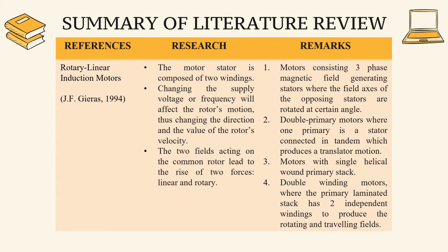Finally, the last study is about the rotary linear induction motors. The motor stator is composed of 2 windings. Changing the supply voltage or frequency will affect the rotor's motion, thus changing the direction and the value of the rotor's velocity. The 2 fields acting on the common rotor lead to the rise of 2 forces, linear and rotary. What we gain from this study is a motor consisting of 3-phase magnetic field generating stators, where the field axes of the opposing stators are rotated at a certain angle.